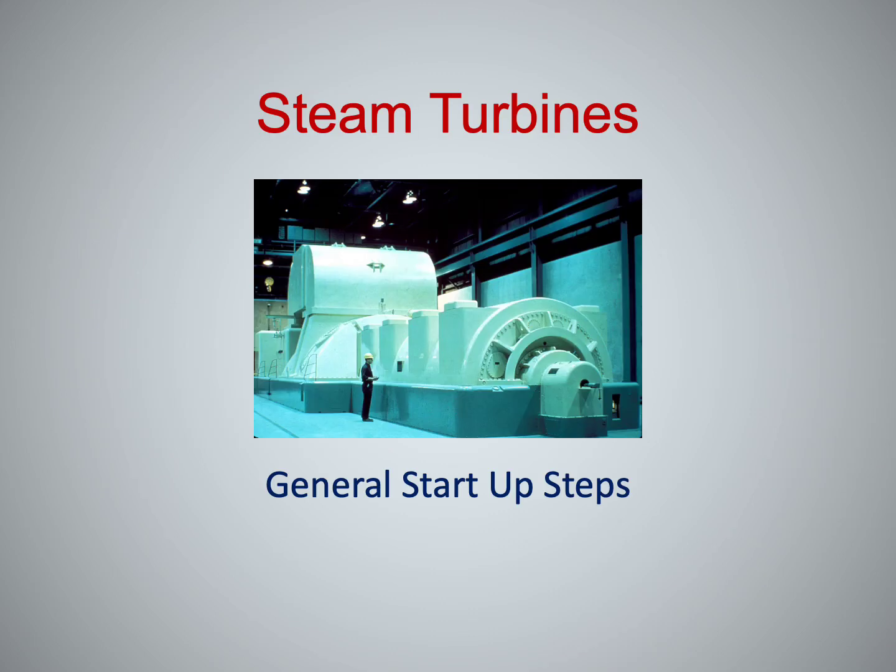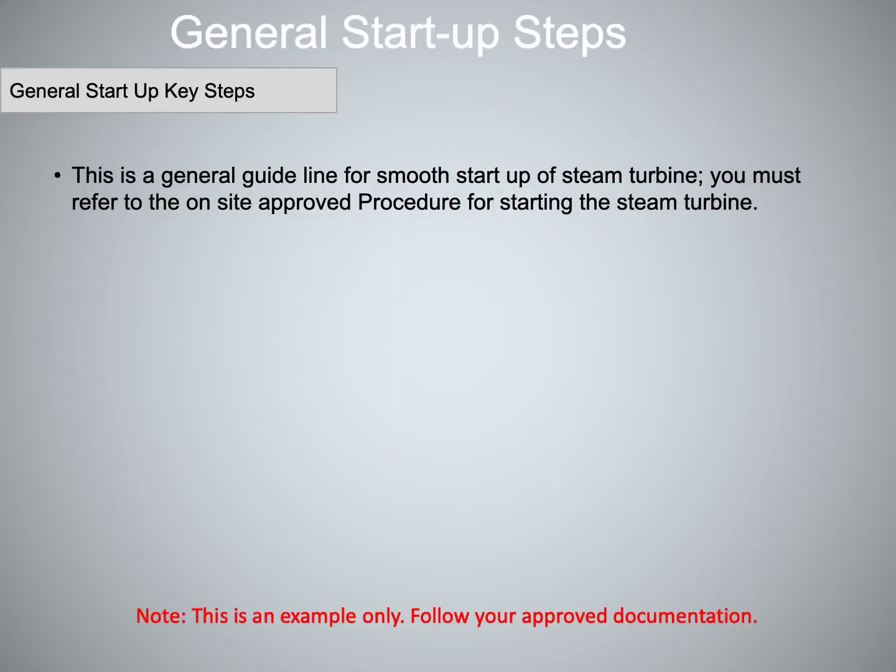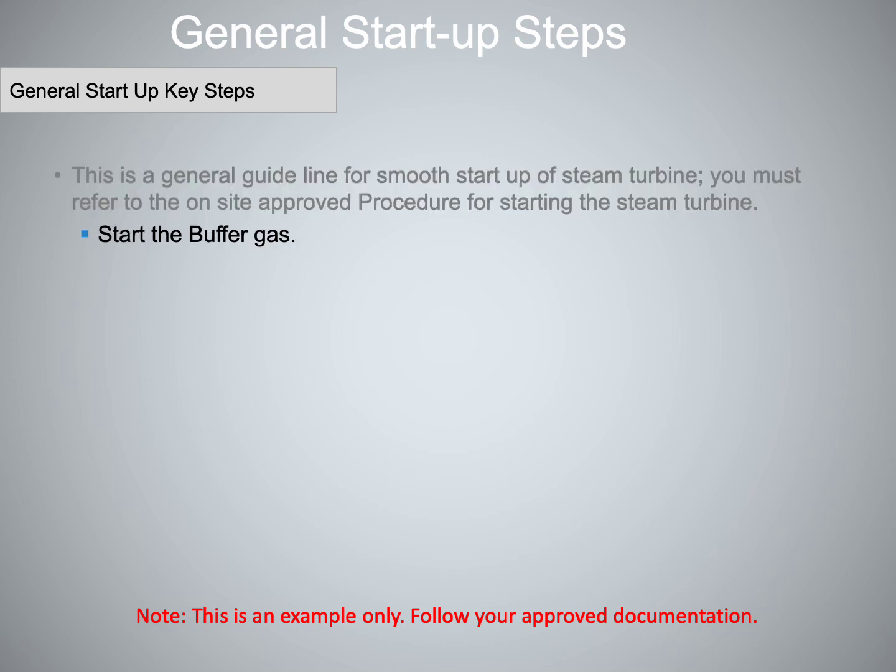Steam turbines, general startup steps. This is a general guideline for smooth startup of steam turbine. You must refer to the on-site approved procedure for starting the steam turbine. Note: this is an example only. Follow your approved documentation. Start the buffer gas.